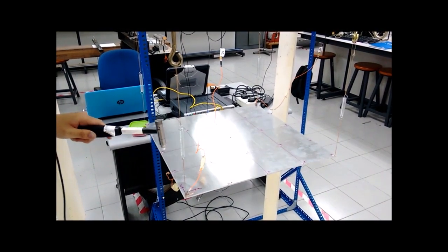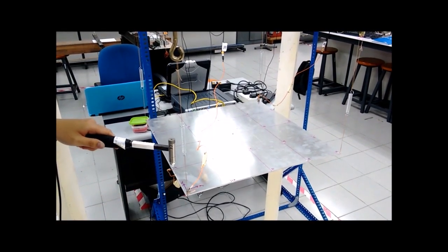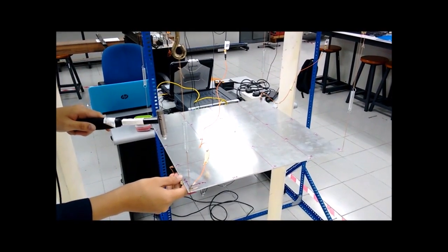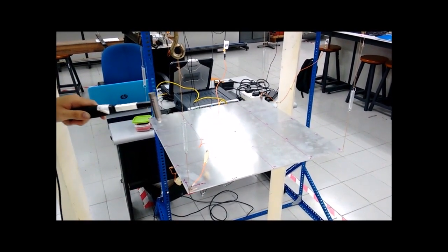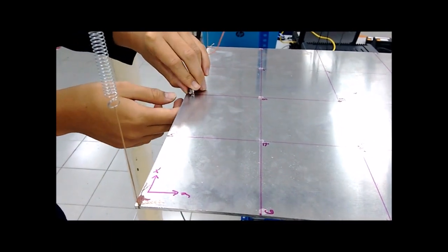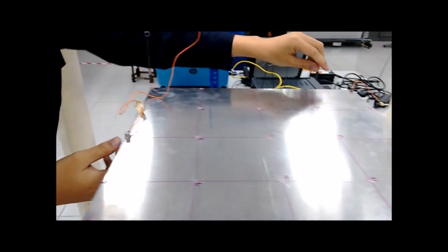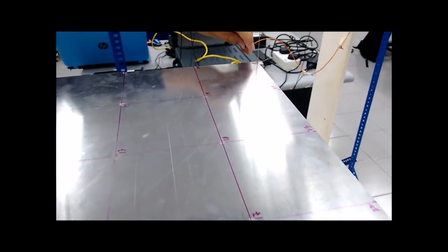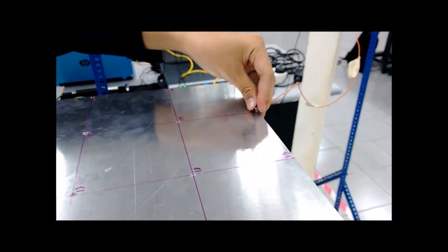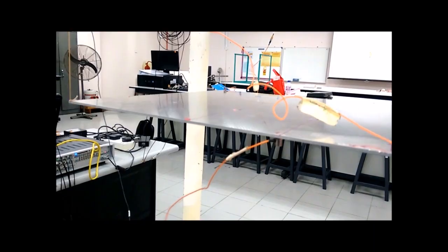The hammer is knocked at the reference position on the structure surface to introduce the force and vibrate the structure. Repeat knocking at least 10 times for 1 run of measurement at each node. This is to get the average reading of the response measured by the accelerometers. Rove the accelerometers to the next node until all the nodes are measured. Make a sequence record for the node measurement to ease the measuring process. A correct hand position when knocking is necessary in order to get a good measurement result.